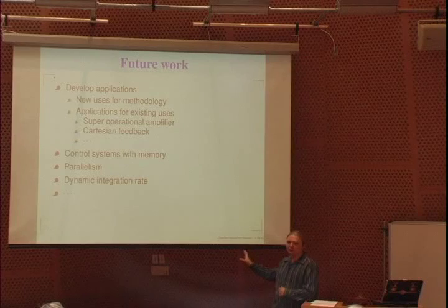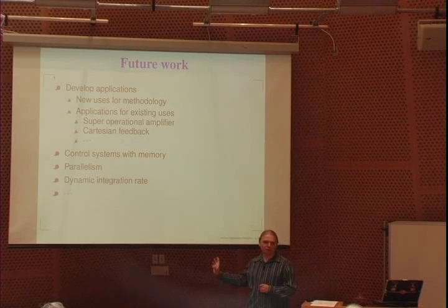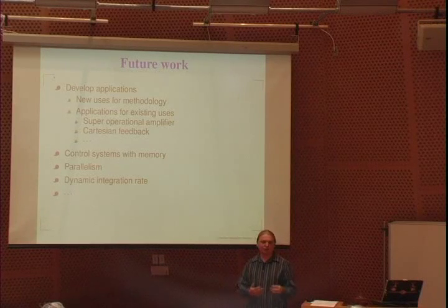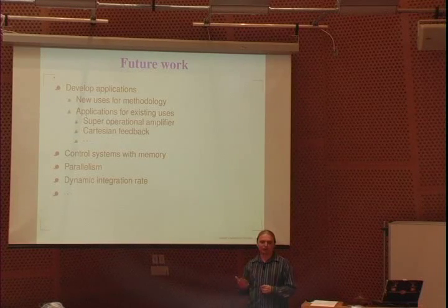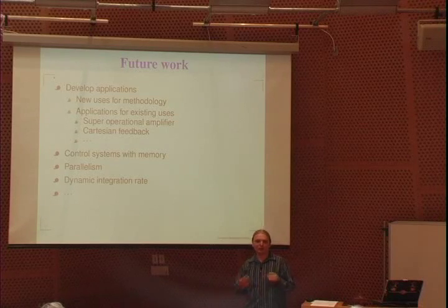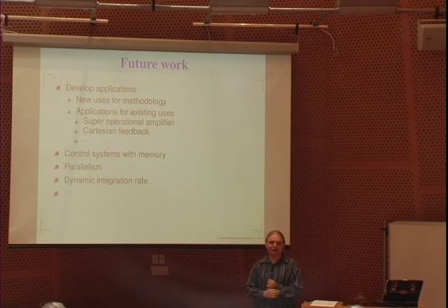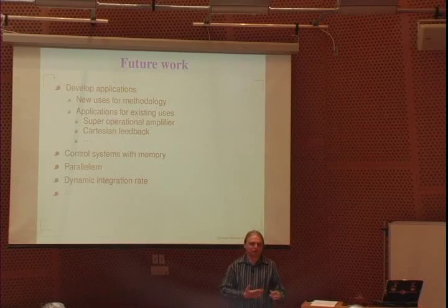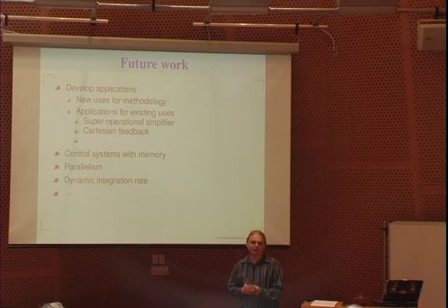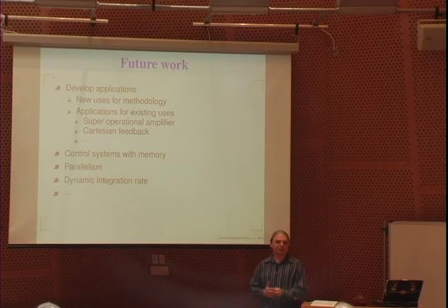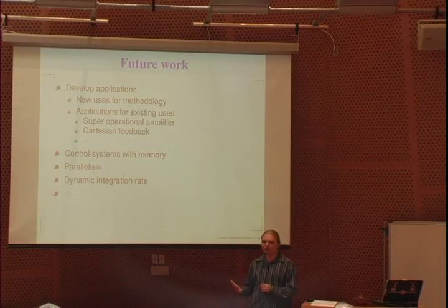A modeling block could model this distortion of a given stage. Here the modeling block doesn't need to run at the full speed of the op-amp, it only needs to run at signal speeds. It could model the distortion of individual stages of the op-amp, and at that point you could adjust bias current levels to try to minimize that distortion and maximize gain. Once you're doing that, you can think about modifying those stages so that you actually have control over the distortion.